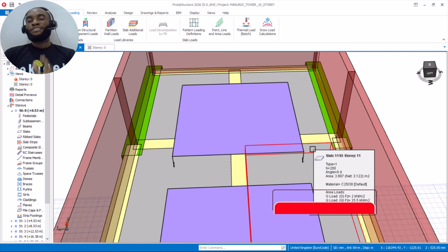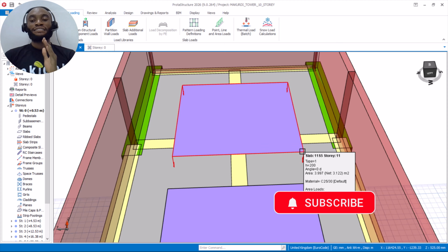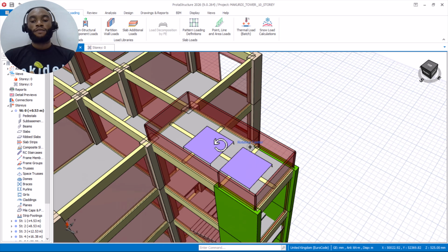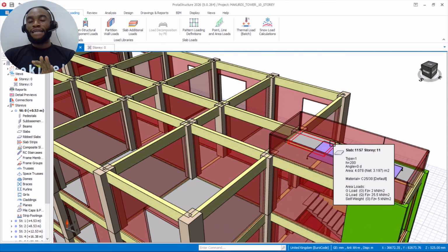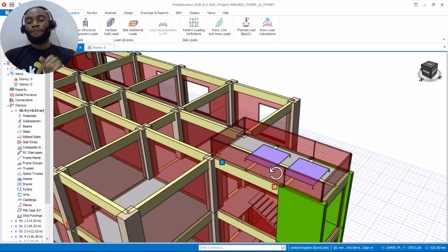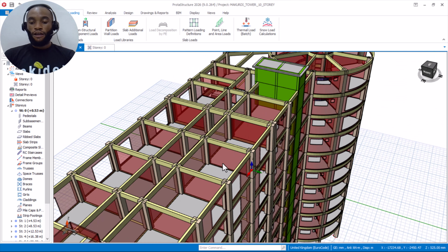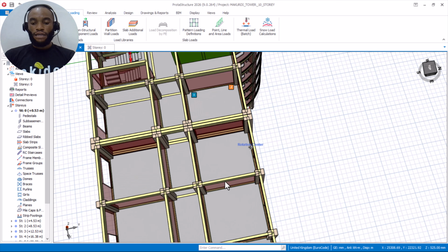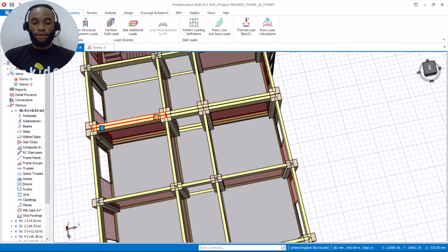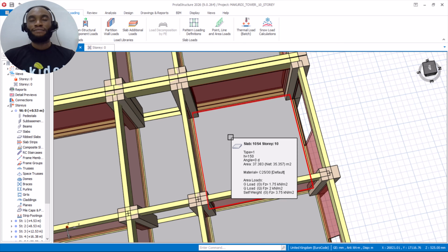But if you have a very vast place, where there is every tendency that the tank is going to shift, then it is best to place the load on the slab. Let me say the tank was to sit somewhere on this whole panel like this. There's a tendency that the tank will shift, because this panel is bigger than the tank, more than 3 times the tank.